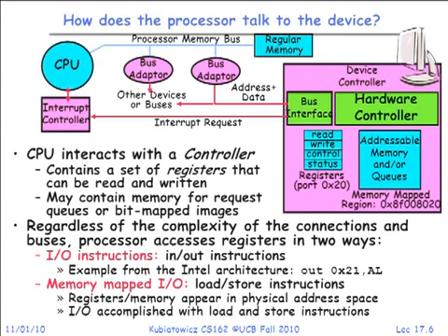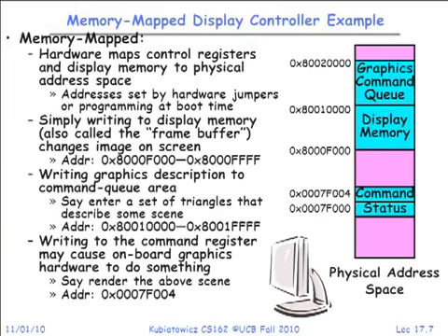Notice that in this particular example, there's actually different types of memory, and maybe not all the types are always writable that way, but oftentimes they are. The second question is, if you've got a gig mapped into the physical address space, yes, it means that there is a gigabyte of physical address space you cannot put DRAM in. And you can start to see why having, say, a 40-bit physical address space might be a good thing, because you can have much more space for devices.